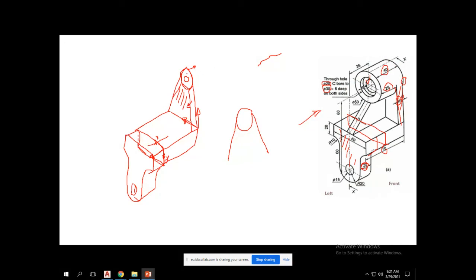So what should we do, guys? I should make press pull in that direction, a distance 5. Do you agree? This is the first press pull. And then make another press pull in that direction, a distance equal to how much? 35, right? So far so good? Okay, now you come to that surface. You see this surface, guys, and you draw the circle of 20 millimeter radius.